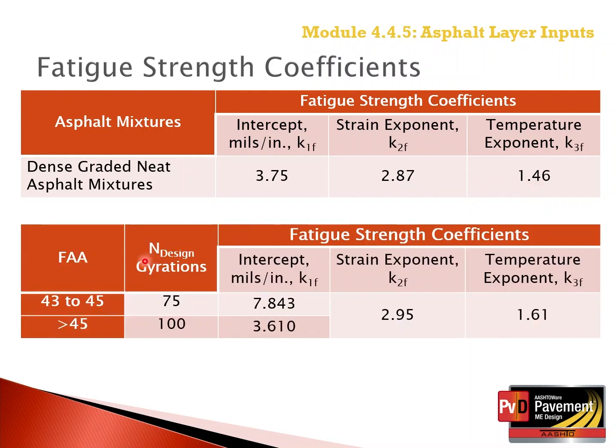The lower table on this slide provides the coefficients of the asphalt bottom-up fatigue cracking transfer function derived for an individual agency that completed bending beam fatigue tests and found the coefficients to be dependent on selected parameters of their asphalt mixture specifications.